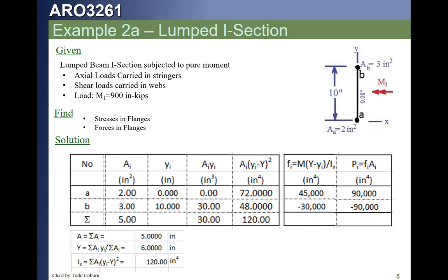And if we went 1 inch into the page, since this is a pure moment, there's no shear on this beam, we'll have exactly the same forces. What this example is doing is teaching us how to plot this out with what's called an exploded free body diagram.